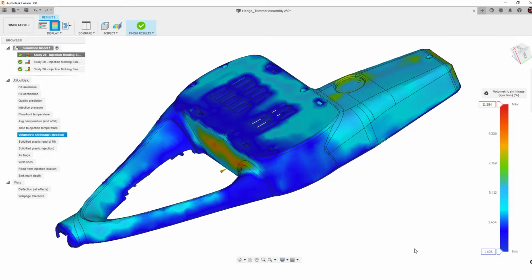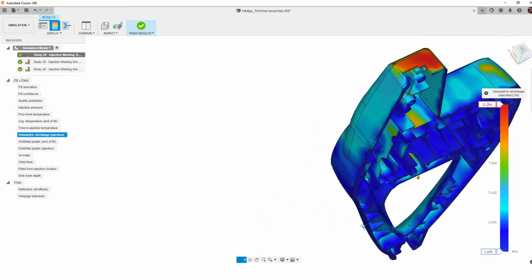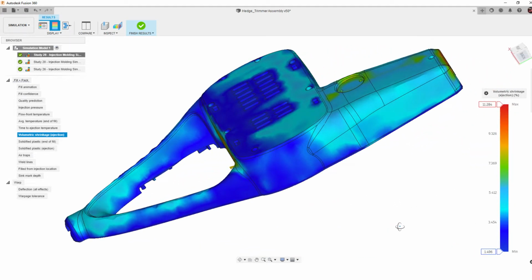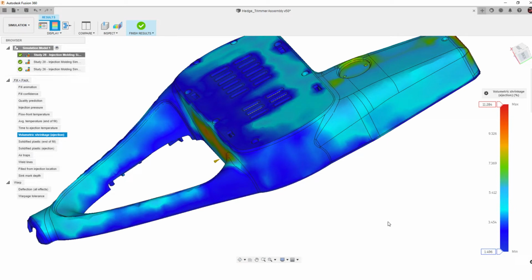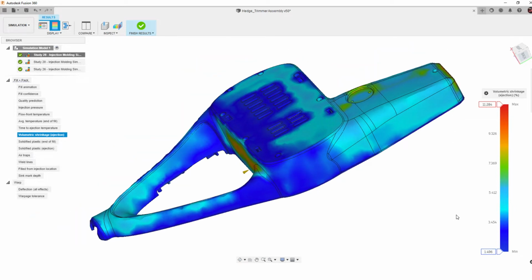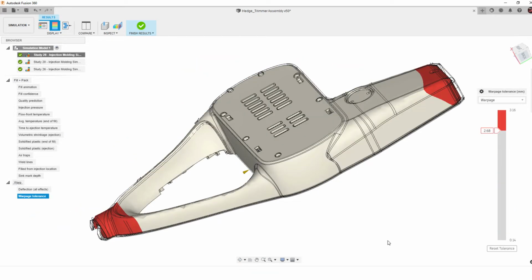While all plastics shrink, several factors can lead to local variations in how it shrinks in a mold as it cools. When some areas of the plastic part shrink differently from other areas, this differential shrinkage can cause the part to warp. Warpage is the out-of-plane shrinkage or movement that occurs as the part continues to cool after it has been ejected.